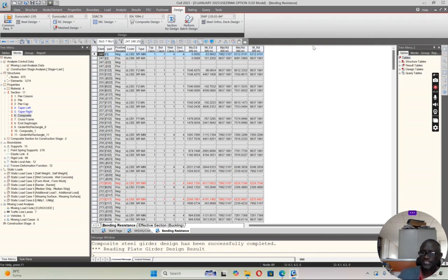So if you have read about steel girder behavior, you will know which part of the girder plays a bigger role in tension resistance, and which one tends to play a better role in resisting shear. Is it the web or the flange? You can design both web and flange to take on moment, or you design the top and bottom flanges to take moment while shear is taken up by the web. Those are things you can do. So this is the first one you can check.